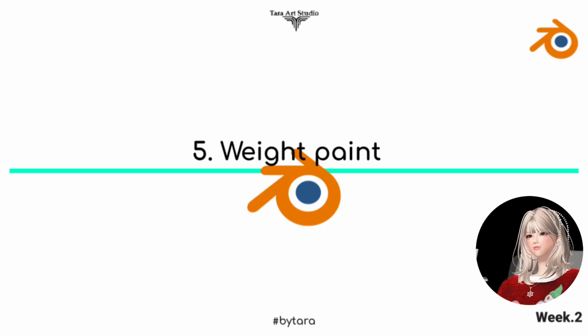You've reached the final destination of this lesson. Before we start to learn weight paint, it's important to realize that the UV editor works as your material map for patterns, graphic placement, and normal maps for advanced level. If you don't have any of those, you don't need to use the UV editor. So don't get stressed out, and think about whether your item really needs UV editing.